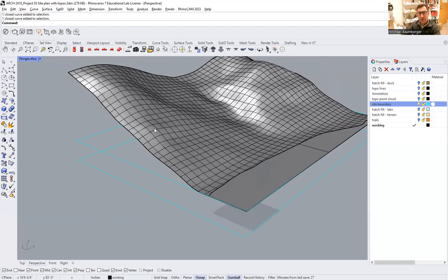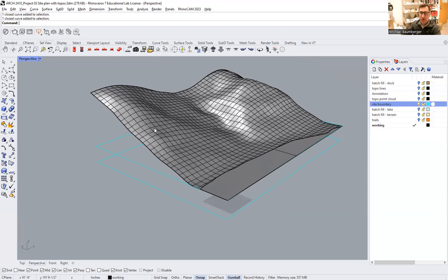Okay, so to finish this out, we still need our enclosed series of faces, right? Anytime you create a solid, it has to be made up of a series of surfaces. If you want to work that way, you could build up a box or any volume through a series of surfaces that are closed and watertight. And then if you join them, it changes its state into the solid. So let's do that.